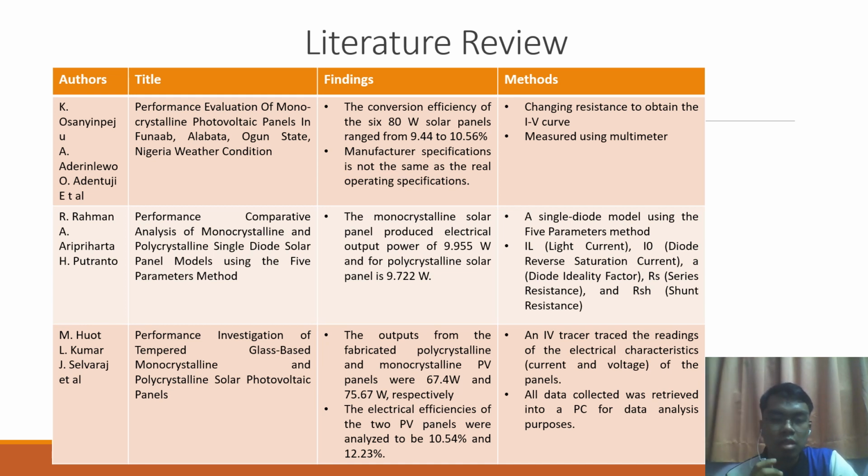The method used in this paper is the single diode model, and they also produce 5 parameters such as light current, diode reverse saturation current, diode ideality factor, series resistance, and shunt resistance.